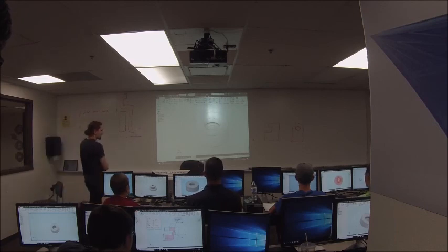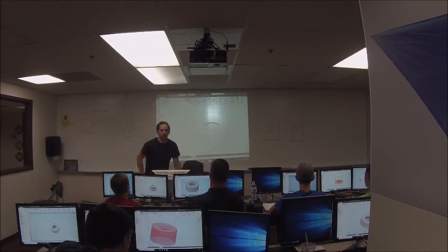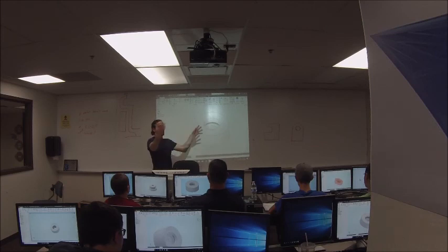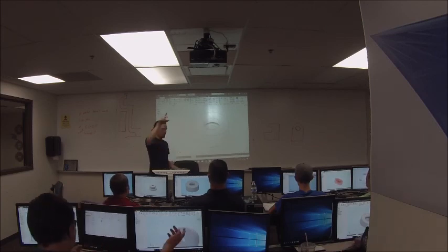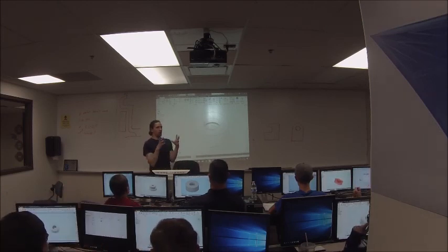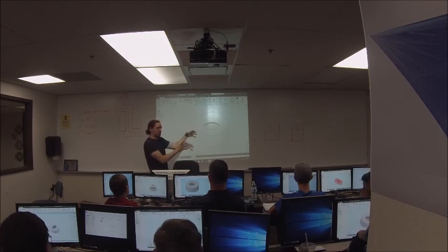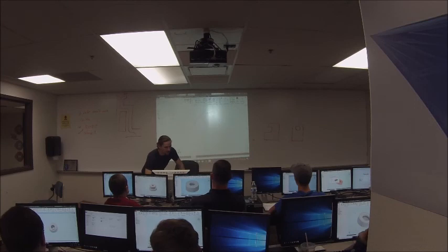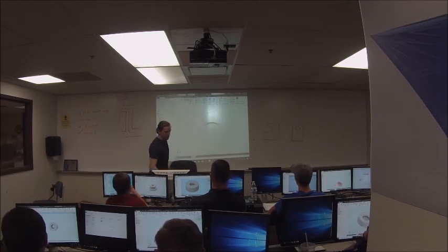Let me do something here real quick, guys. This is going to be important for when you guys are working at home. Okay, let's say I have a profile and I extruded it, but I want to revolve it instead or something. Like I don't want to delete my sketch, right? Because if I just go over here to Revolution 1 and right click, delete, click OK, it just deletes the whole thing. My sketch is gone, my revolution is gone. That's not what I want. I want to delete the revolution, but I want to keep the sketch.